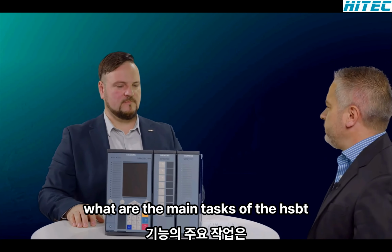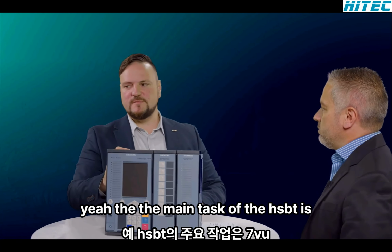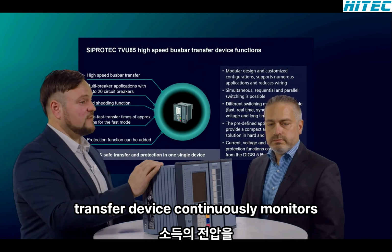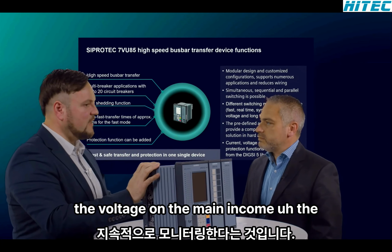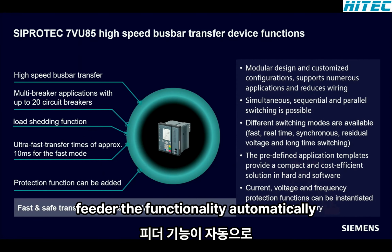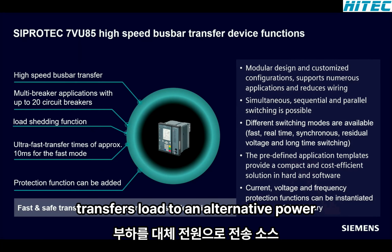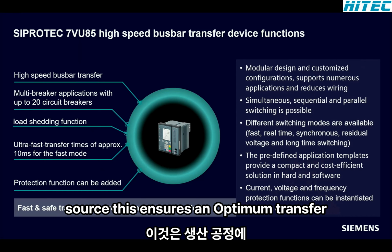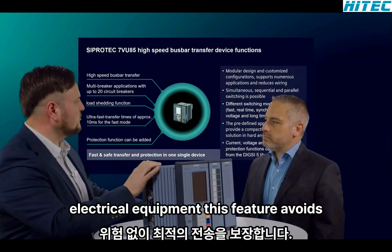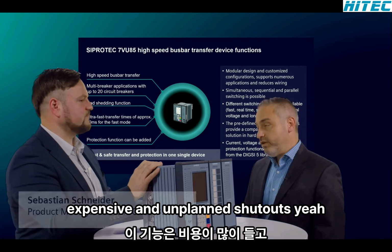And what are the main tasks of the HSBT function? The main task of the HSBT is that the 7VU high-speed busbar transfer device continuously monitors the voltage on the main incomer, the motor bus, and the alternative incoming feeder. The functionality automatically disconnects a faulty incomer and transfers bus load to an alternative power source. This ensures an optimum transfer with a minimal impact on the production processes and no risk of damaging electrical equipment. This feature avoids expensive and unplanned shutdowns.